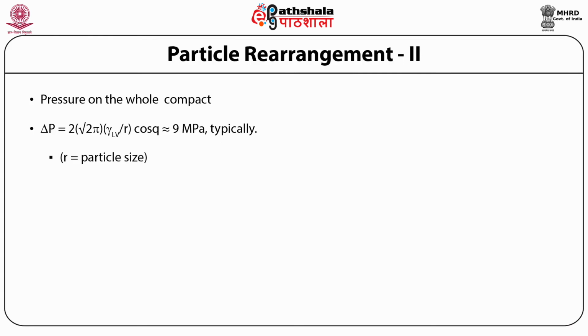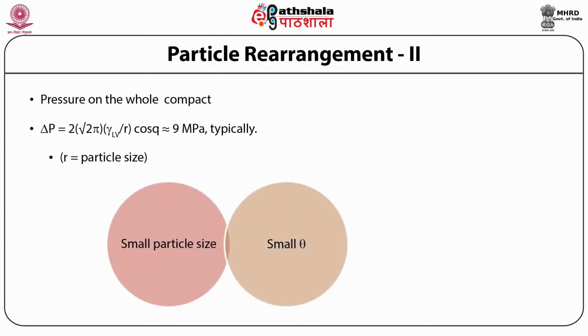The above relation shows that effective particle rearrangement is favored by a small particle size, small contact angle, and a high value of liquid vapor surface energy.